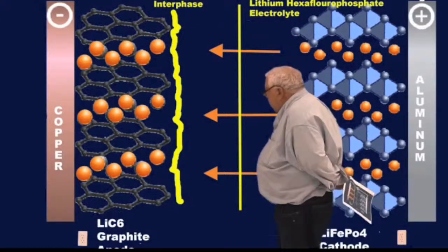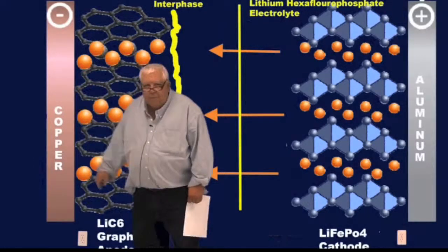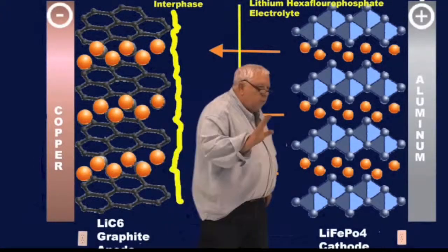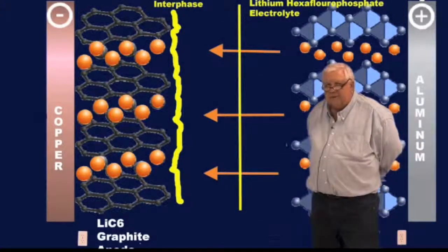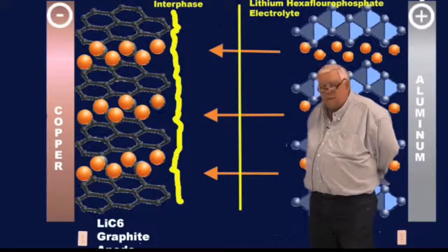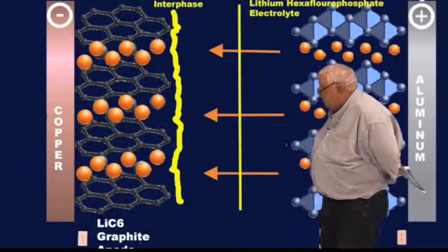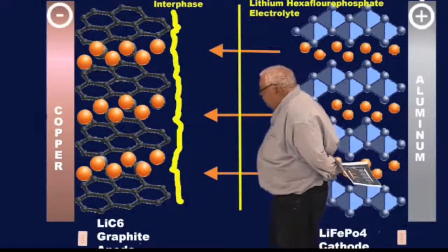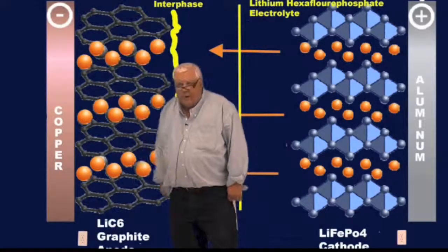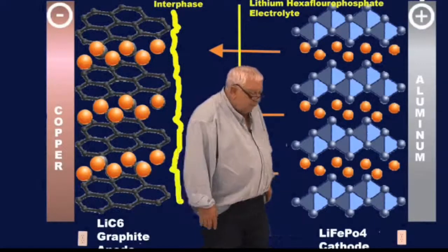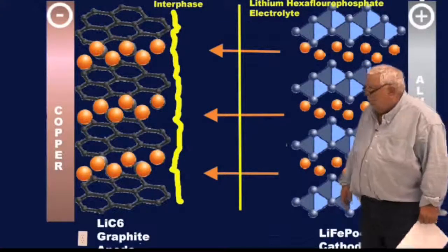And so each time we move lithium ions through here, it thickens this SEI layer. The initial one is the big laydown of the solids. After that, it slows down quite a bit. But that's part of the aging of the battery and the increase in impedance, or as so many of you insist on discussing it, internal resistance, but it is a diffusion delay and a little bit of a drop there in the battery that thickens and increases with age and which causes the battery to age more.